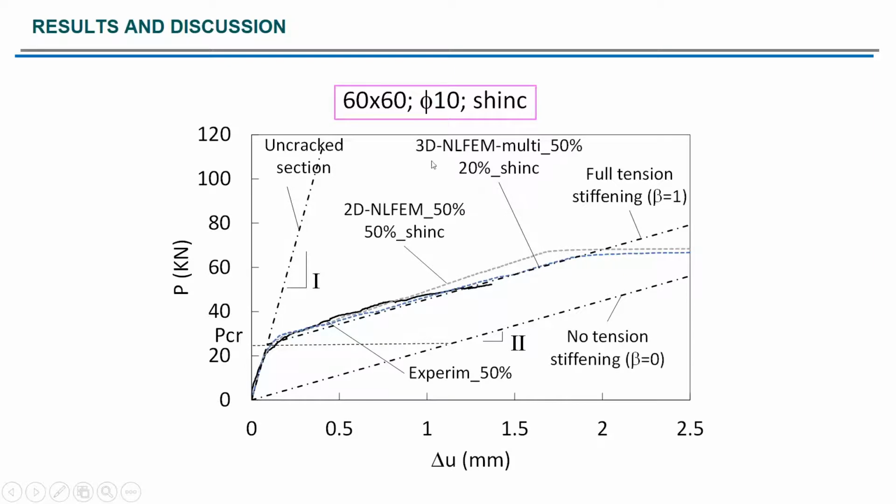The only thing is, if we compare the 2D and the 3D model, the fit due to the effect of shrinkage is a little bit different. In this case, the percentage increment for the case of Eurocode 2 was 50% for the 2D case, but only 20% for the 3D case. That means that the 3D effects in this tensile test are important, so we could say that this is the more accurate and precise model to characterize these tensile elements.